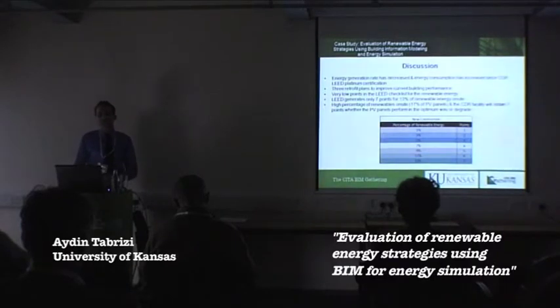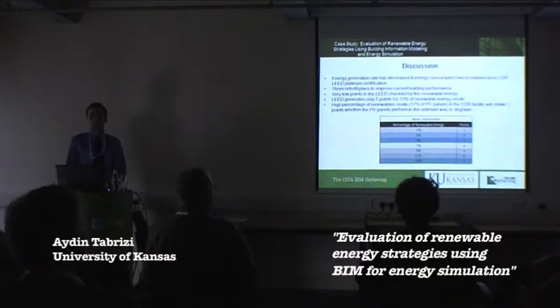So in our discussion, we evaluated the LEED criteria, and as I said in the second slide, we have just 7 points for renewable energy under LEED. Basically, when we have 13% of renewable energy, whether it's wind or solar or any type of renewable energy, we can get those 7 points under the LEED criteria. And we noticed that this is not giving any incentives to people to consider improving, increasing or replacing.